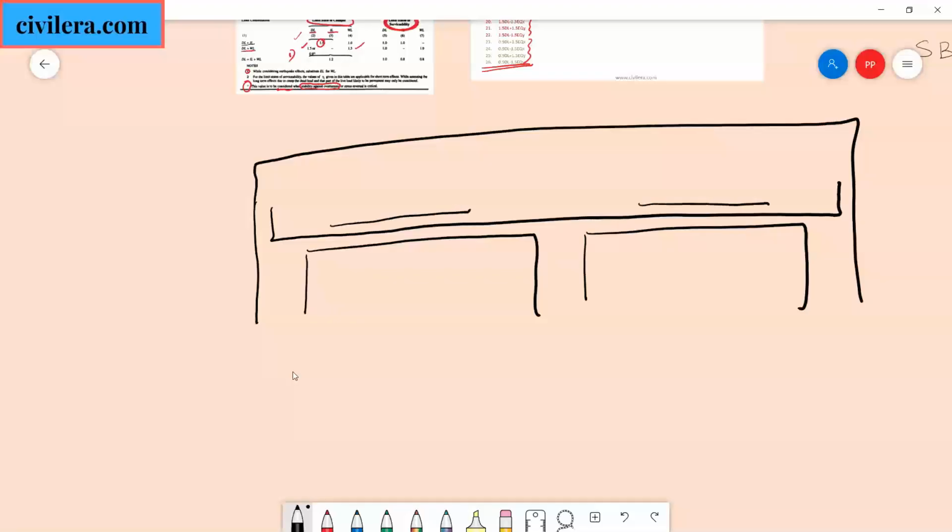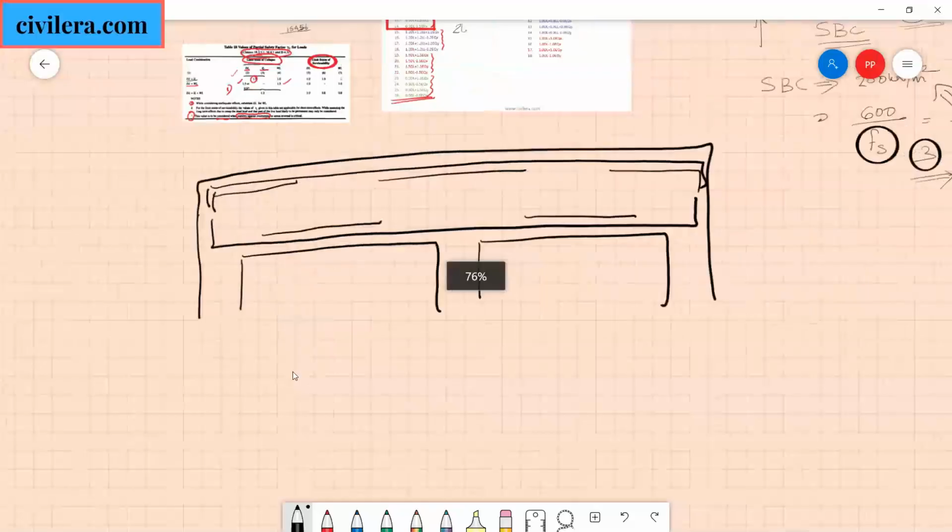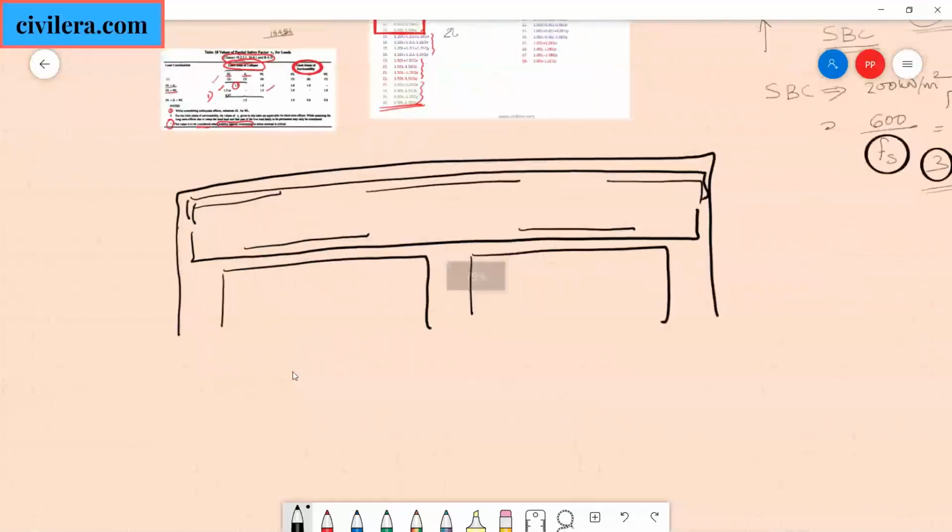You have a through reinforcement, you have an extra bar, an extra bar, an extra bar. This would be the standard way of detailing. Why is it so? Because you have tension here, here, here, here, and here. So this will be the standard detail of your beam.